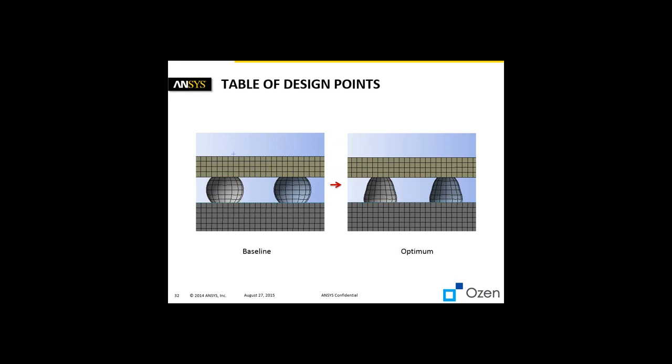And what kind of solder? Like eutectic? Eutectic, right, yeah. It melts at 186 degrees Celsius, or I forget, reflow temperature I believe 217 degrees centigrade, something like that. So did you have to turn on the creep effects for that material? Not for this case. We just wanted to do this as an example. Oh, okay. But in real life, when we do this, we do viscoplastic simulation.